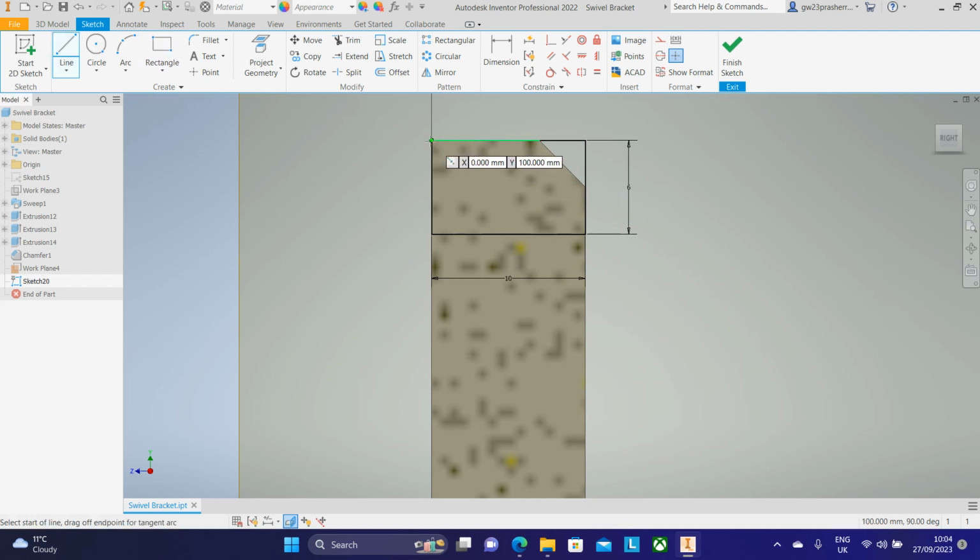So using my line tool, the first thing I'm going to do is go down 3, and then I'm going to go along 5, which will be a height of 3. So I'm going to use the line tool, and I'm going to change my angle to 45, and it's got a height of 3, which means that all we need to do is click where it hits that bottom line. So I've got my rectangle 10 by 6, and then I've gone down 3, along 5, and then setting my degree at 45, I've got my line here.